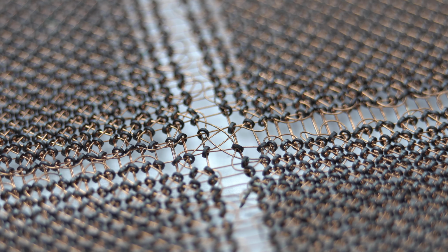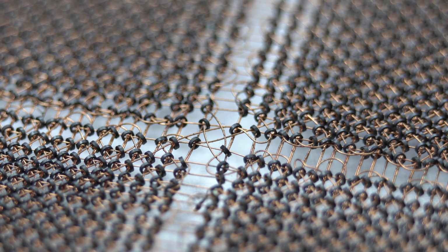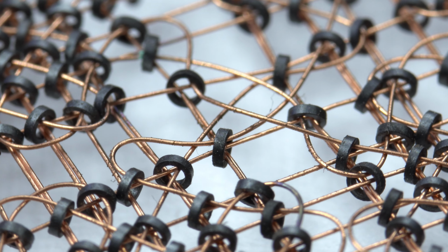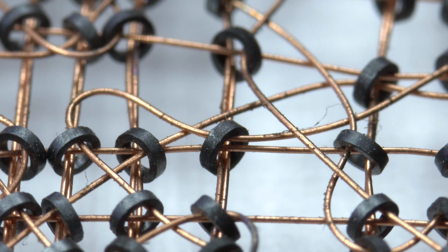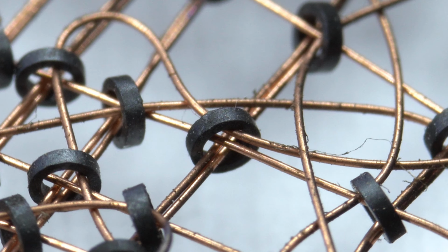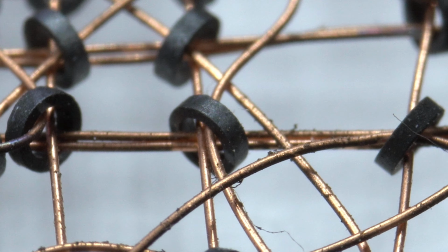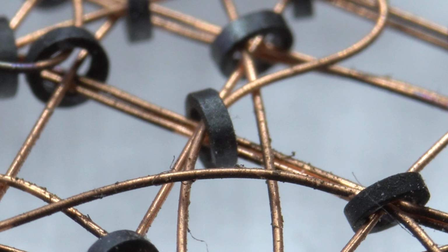You could use magnetic core memory. Magnetic core memory was one of the earliest forms of computer memory, and it was known for being very radiation resistant. One of the reasons for this is simply due to the fact that the toroidal cores used to make up the memory are physically very large. One stray radiation particle is not enough to disrupt the magnetization state of the entire toroid.